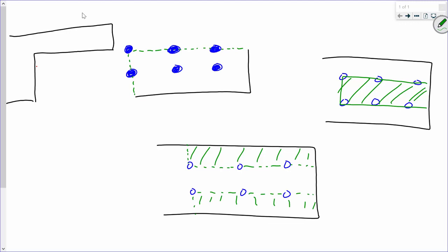So whenever we do a block shear, will it kind of be like the last part on the homework where you gave us like 5 inches between 2 lines of bolts and you kind of know what block you're going to go off of? You should give us the distance from like the lower. Well, that's a good point. I didn't give you that distance, but think about it like this. It was a C15, right? So once you designed the section, you'd know the actual depth. And it stands to reason that it's going to be in the middle. Do you see what I mean?